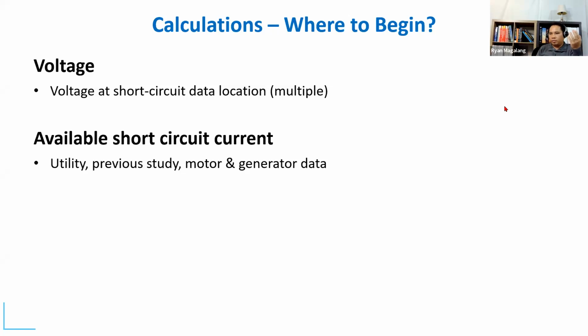So now let's say 10 years from now, more residential areas have been established, more businesses have been established over the vicinity. Now the utility would have to construct, upgrade the substation, maybe make it 100 MVA, and that's the reason. Connect the grid, draw more power from the grid, and that's the reason why the fault current in that area suddenly increases.